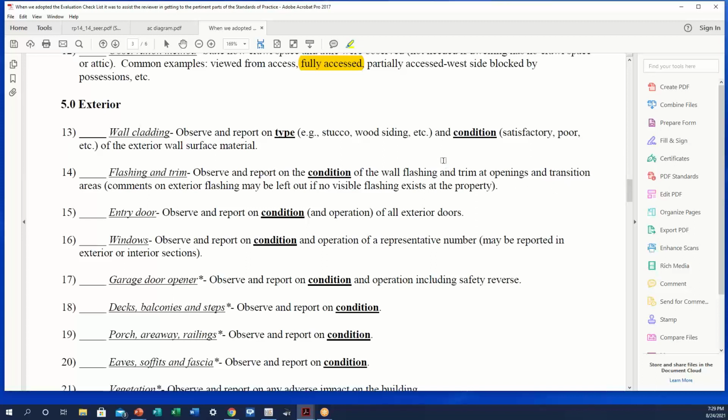Trim. Stucco doesn't have a lot of trim. We're trying to get rid of all wood. The builders would like to get rid of all wood if they could. But what about the pop-outs around the window though, Greg? Yeah, that's the next thing here. The pop-outs around the windows and stuff, that's still trim, everybody. And the builder isn't following the rules of what the manufacturer says. And if you don't know what those are, we'll do a whole class on what the manufacturer says needs to be done as far as flashings under the stucco and counter flashings to make that water drain out around the window instead of back in through the frame.